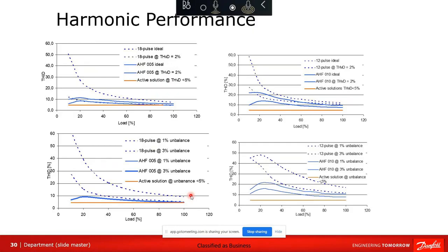The benefit for us as salespeople is that all of those Robicon drives from 20 years ago and less are now 15 to 20 years old, and they're all approaching their end of life cycle, and they're all large. And if you have any of those out there, we can easily leave the panel in place, take the drive out, take the phase shifting transformer out. There's boatloads of room in those panels. Put a Danfoss drive, or if you elect someone else's drive, and a passive harmonic filter, and there's still plenty of room left over. So you can retrofit those panels very easily.